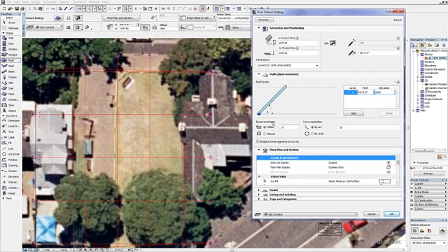If the eave overhang is 450 mils, then you can type in here 450. Whereas previously in ArchiCAD version 13, that was not the case. You couldn't specify for, say, a single plane roof, the offset in this window.